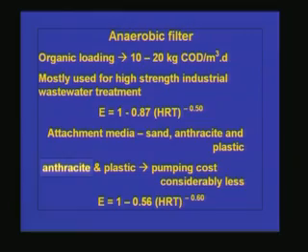The efficiency of the anaerobic filter can be found using this empirical formula: E is equal to 1 minus 0.87 HRT raised to minus 0.50. Here HRT should be in hours. We have seen in anaerobic lagoons the efficiency is given by an empirical formula where the HRT was given in days, but in anaerobic filter the HRT is given in hours.